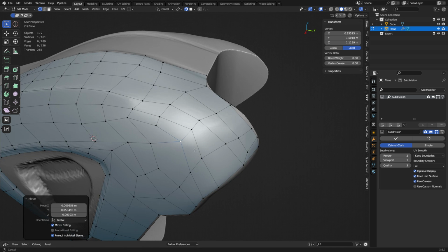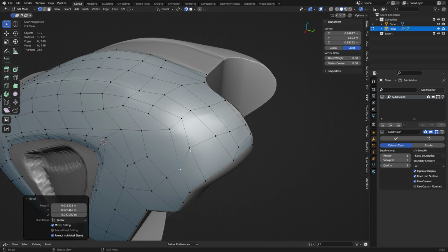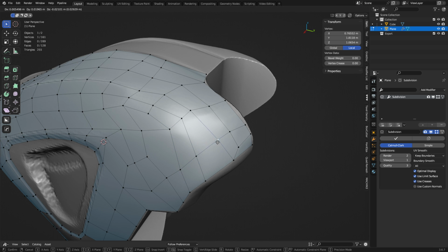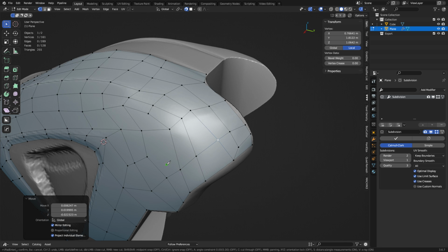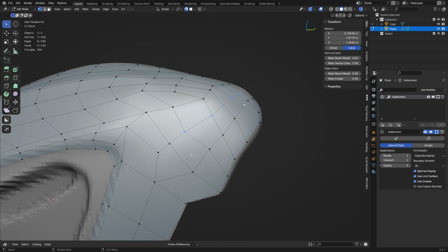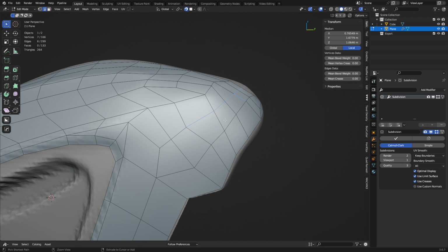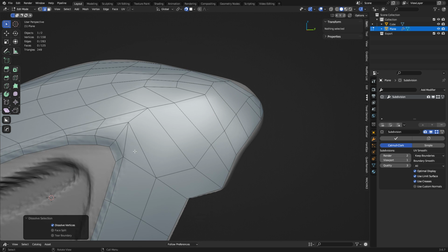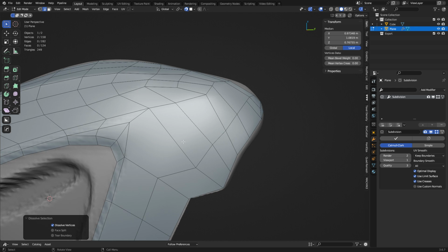You see, it's all about balancing now, right? We're trying to balance this area. I was trying not to send a whole edge out. I was going to do maybe something like an inset. So if you didn't want to send an edge out at all, let's say we just got rid of that. We had this whole area back to an N-gon. We could do something like this, where maybe we stop here. We'll get two end poles out of it.